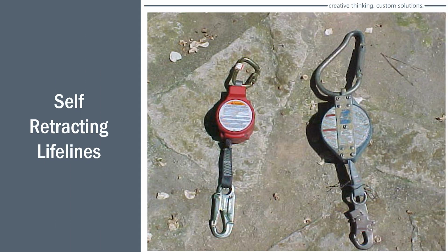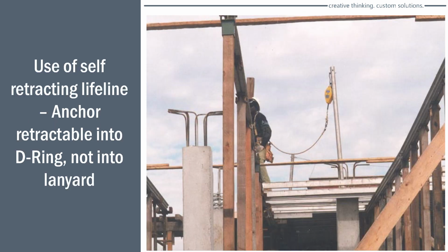A couple of different types of self-retracting lifelines. Now, this next picture I'm going to show you, what do you think? Look what the person's doing. He has a self-retracting lifeline and he has a lanyard. The lanyard is connected to the self-retracting lifeline. That's a no-no.